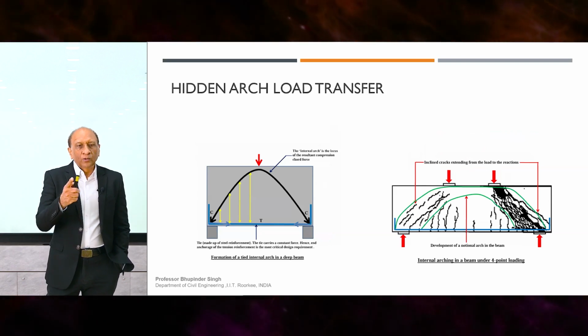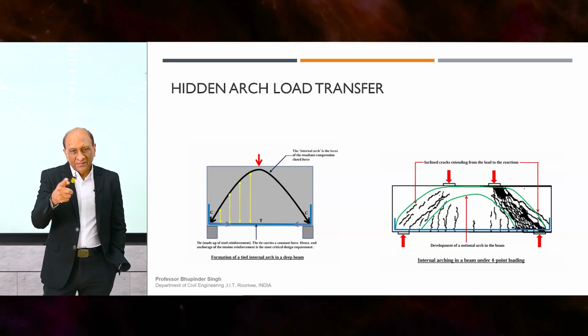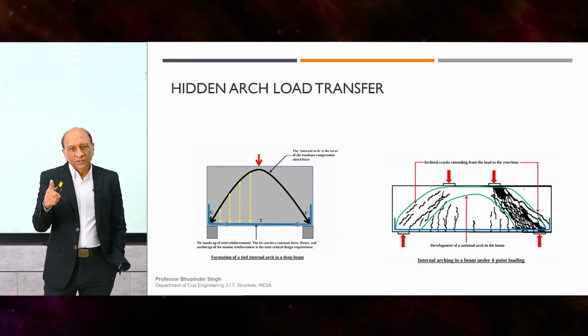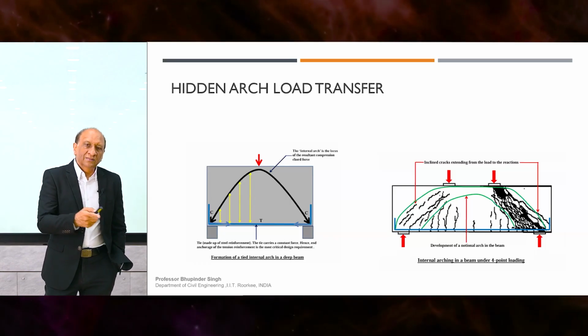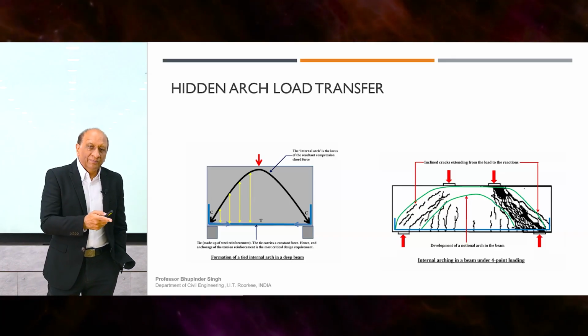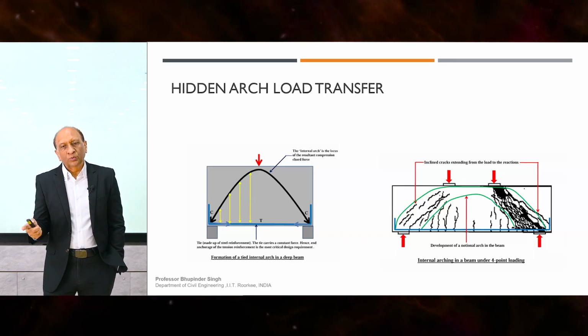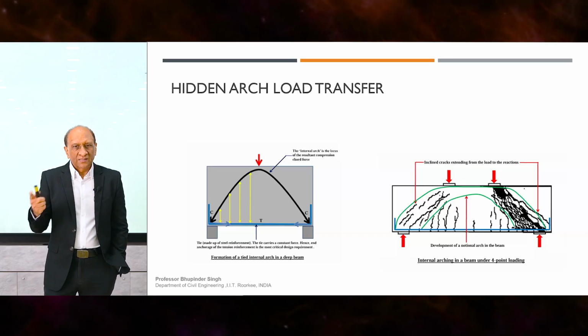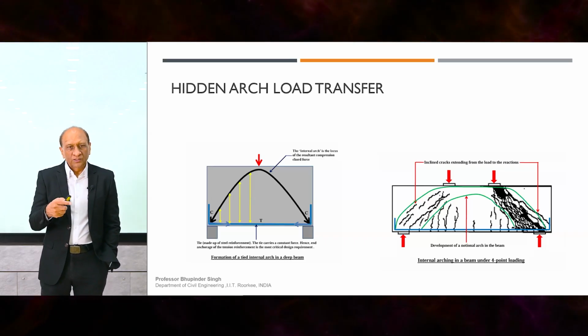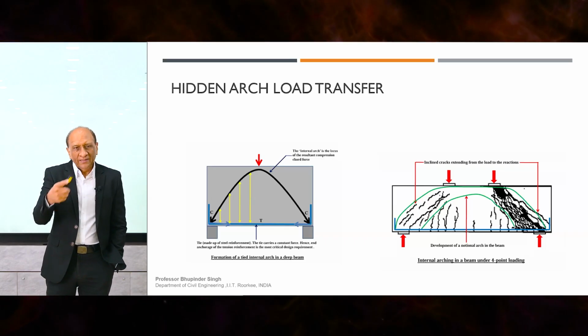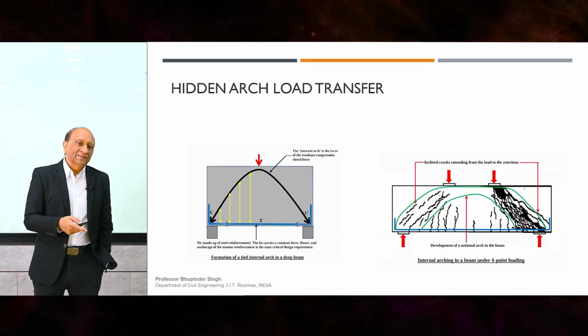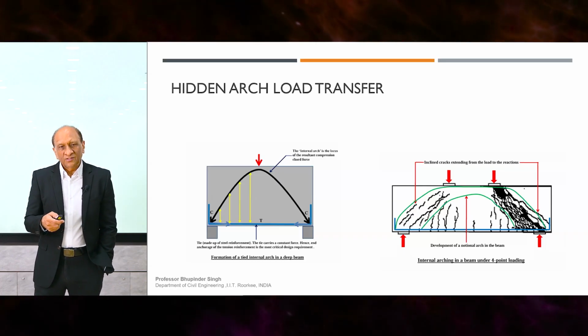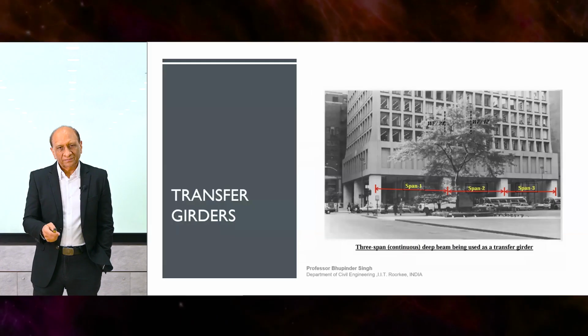is quite similar. The only thing is that you can see from the patterns that you can connect them through a strut, or you can assume it to be an arch, a tied arch. The end result is nearly the same. So these are two internal mechanisms that you could think of when interpreting the internal stresses and the crack patterns.